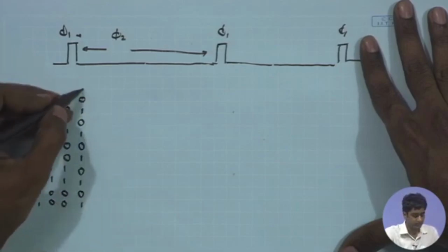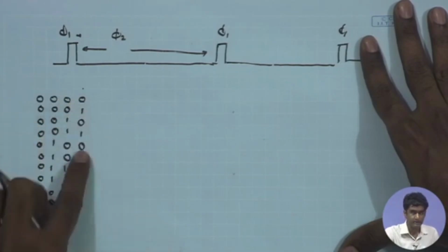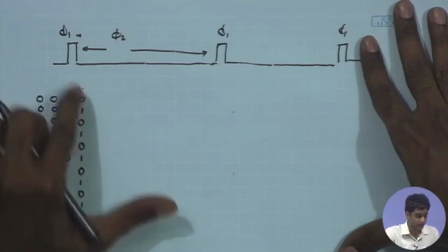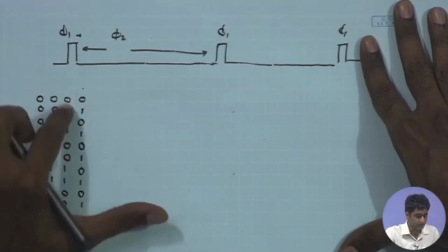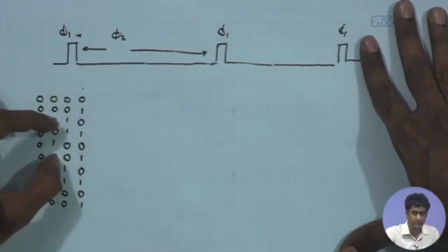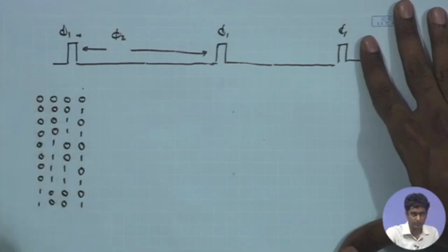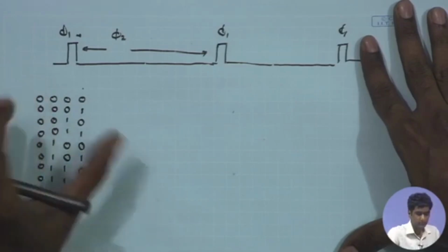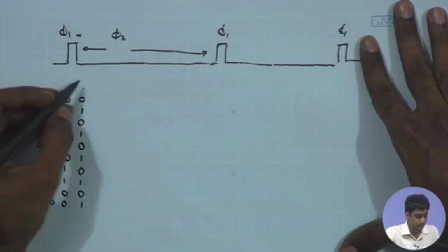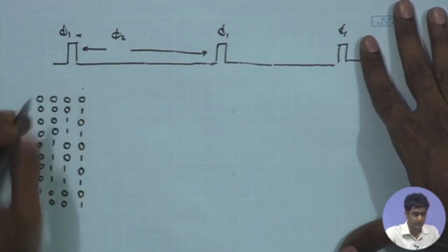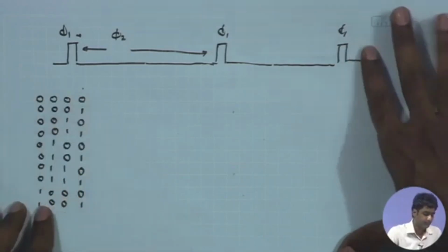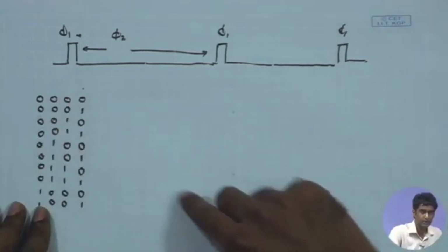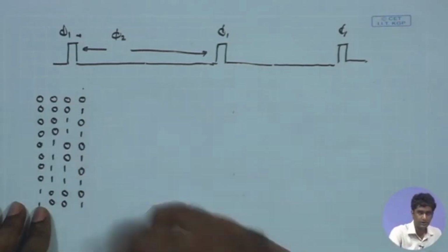So, this is the LSB, the least significant bit, alternating every clock cycle: first clock cycle if it is 0, next 1, 0. Likewise, the second one alternating every 2 clock cycles, third one after 4, fourth one after 8. So, this is the operation of a counter. If these are the 4 bits coming out of my counter, I expect this behavior from each of those 4 bits.